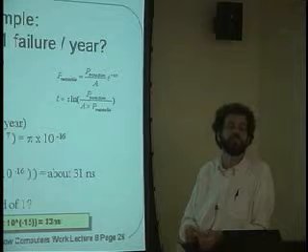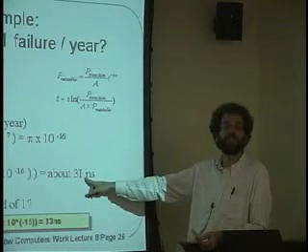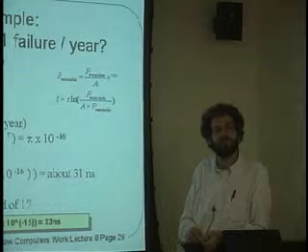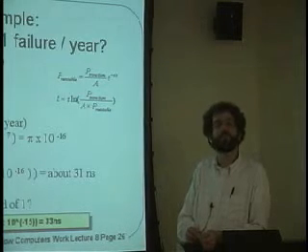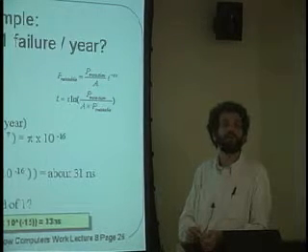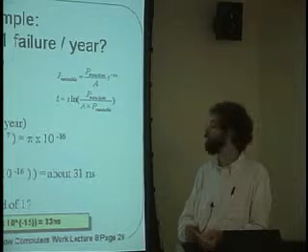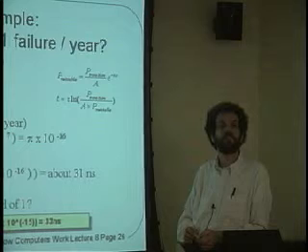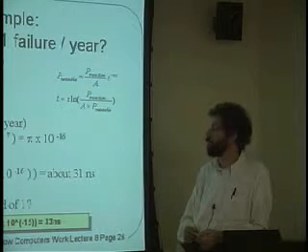in terms of a processor, for instance, that's going at 100 megahertz, or these days, one that's going at a gigahertz. This is 31 clock cycles for a gigahertz processor that need to be wasted while idling away, waiting for the flip-flop to come up with the answer. And while we're waiting for it to settle down with the answer, we could be doing other work. So we're going to have to figure out some way to fix this.